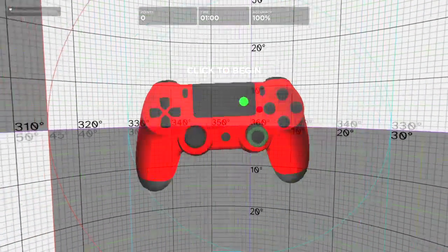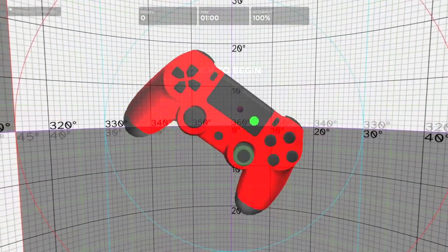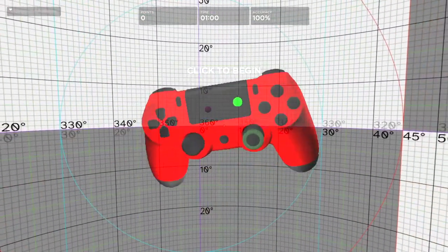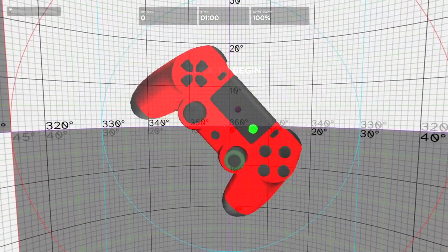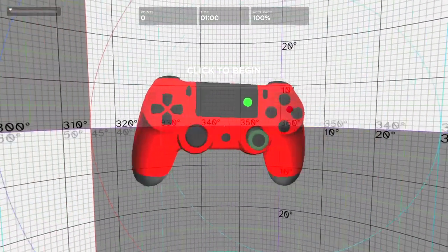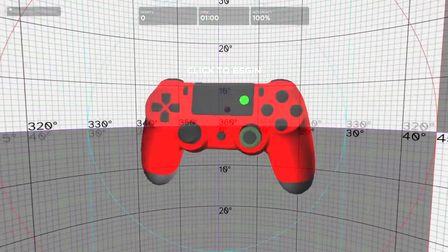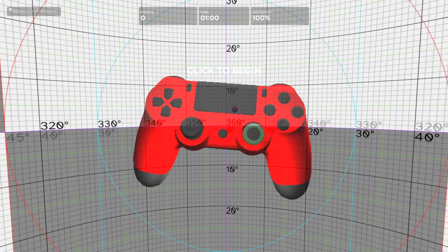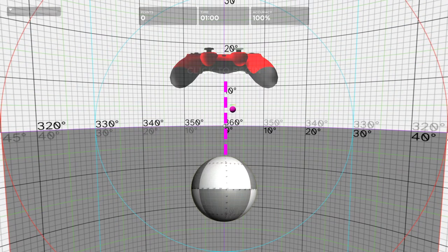In just about every controller that's not Xbox, we have a gyro and an accelerometer. Conveniently, the accelerometer can determine the direction of gravity using it as a fixed point of reference. Combining that information with the gyro sensor, we can ensure that yaw rotation is always relative to gravity. So how does this work? Here I've set up a visual metaphor of what's going on.